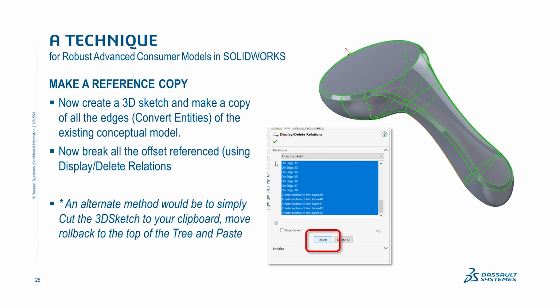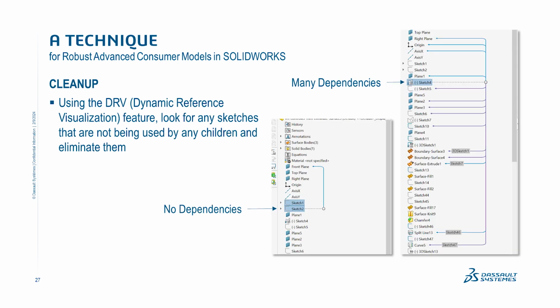So now that we've deleted all our surface features, the next step in all of this is to build your curve network. Okay, so it's that time to start going through your tree and repairing those curves, those sketches, and make it a unified curve network. And so we can start to go down our tree and start to rebuild our curves.